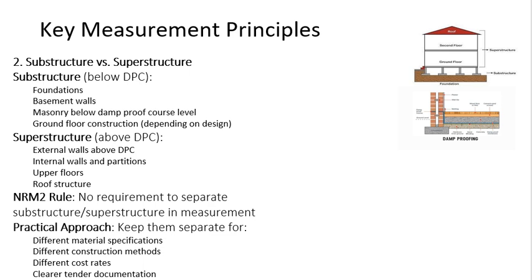Okay, in NRM, masonry is not separated for substructure and superstructure. We know concrete is, right? There are different categories of concrete. One applies to column, one applies to foundation. For masonry in NRM, there is no such thing. So the same section 14 and the same item of masonry will give you the description of the wall, superstructure as well as substructure. Got it? So you don't have to look into different sections for different types of structure.